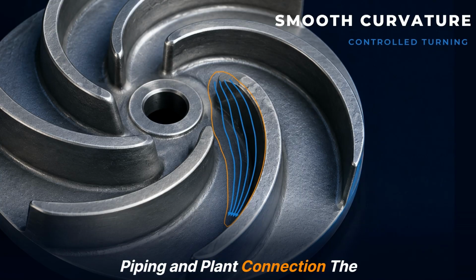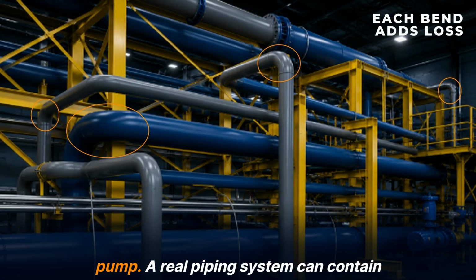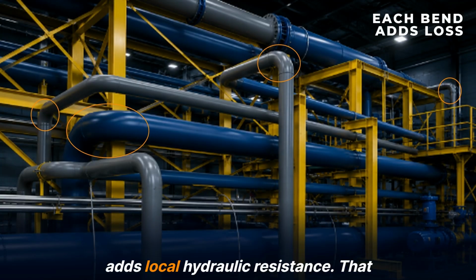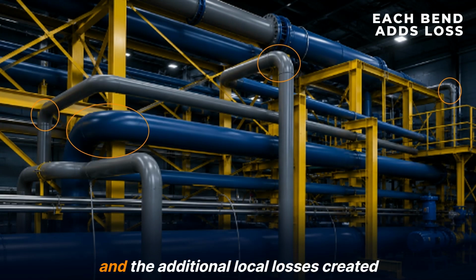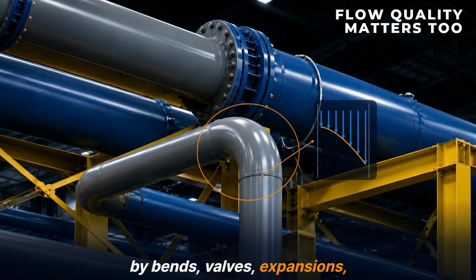Piping and plant connection. The same principle also matters outside the pump. A real piping system can contain many elbows and fittings. Each one adds local hydraulic resistance. That means the pump must overcome both the friction losses along the straight pipe and the additional local losses created by bends, valves, expansions, contractions, and other fittings.